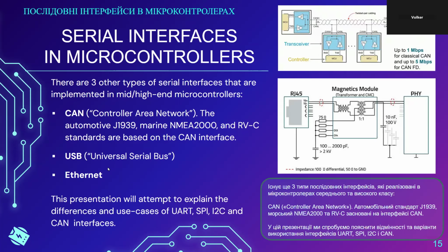USB, we're using it every day, but in many embedded systems, it is actually not a very useful bus. It is primarily useful for connectivity to larger PCs and higher end devices. The problem with the USB bus is that it's very PC centric, but most importantly, the distance. USB has a fairly limited maximum cable length.